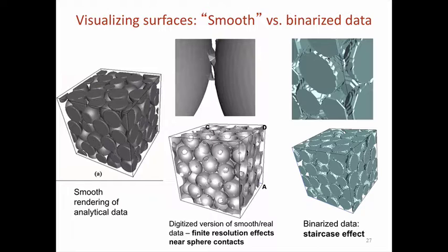Permeability in itself doesn't really care what happens next to surfaces all that much, but mostly what's happening in the major pathways through the middle of the pore space. The middle of the pore space carries most of the flow, typically 90% of it, and the inertial effects in these corners are not a huge deal.